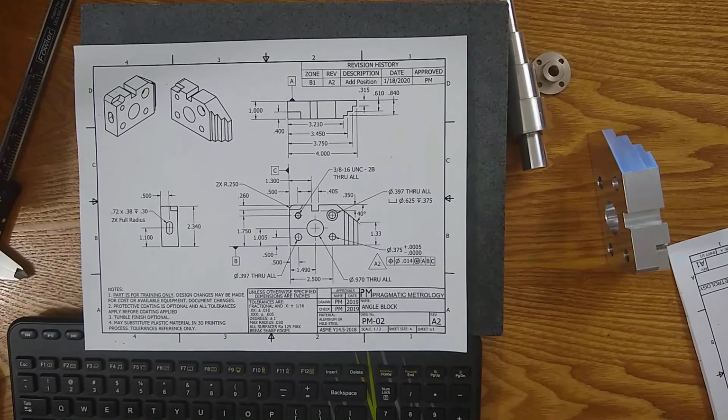What I'm calling a precision hole is just anything that has a tight tolerance diameter and a good surface finish. A precision hole could be milled, bored, turned. I'm not a complete expert on machining, but boring bars or reamers, end mills, anything that leaves a good finish and leaves a precision tolerance. So these are the ways you might see it called out. Different styles.